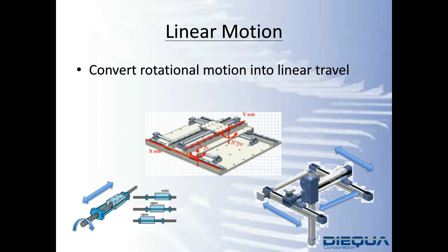And the idea would then be to take that rotational element and, whether it's through a rack and pinion, ball screw, conveying, a belt, chain, and sprocket, you accomplish this linear actuation, if you would. So the focus will be what gear trains will help you accomplish that motion from motor to linear, and also what mounting between the motor and the linear aspect will help you facilitate that aspect.